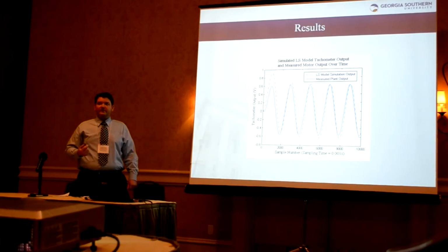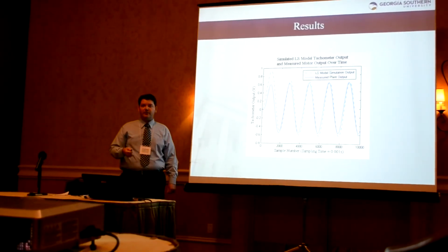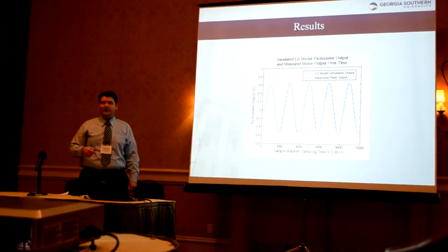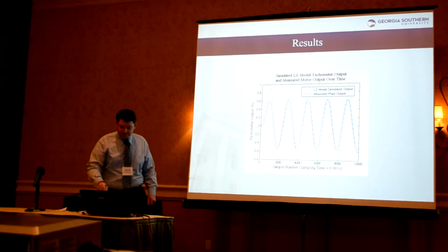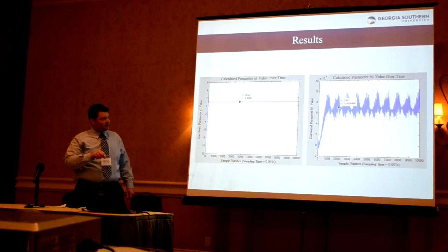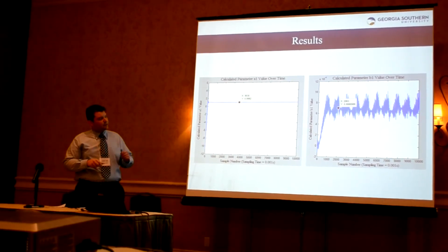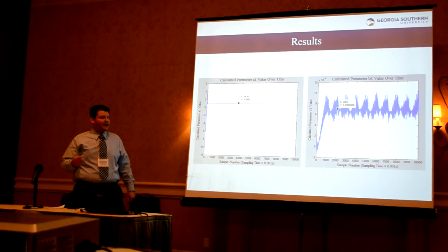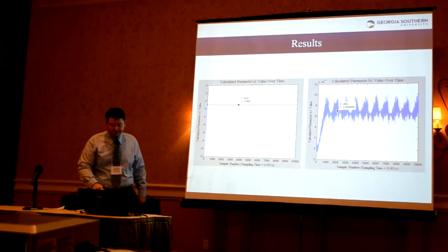There is a dead zone effect, or a presence of higher order dynamics at the actual starting time of the DC motor that the model cannot account for, as we modeled it as a first order system. Also, you can see this effect in the first second of simulation. As I was talking about earlier, it takes a second for the algorithm to calculate that oscillating region of the parameter B1 value.